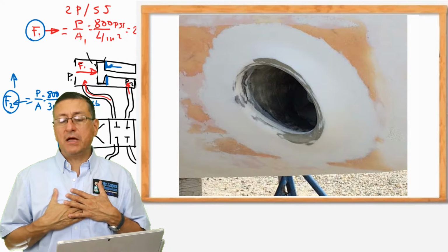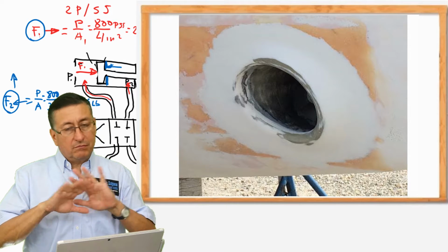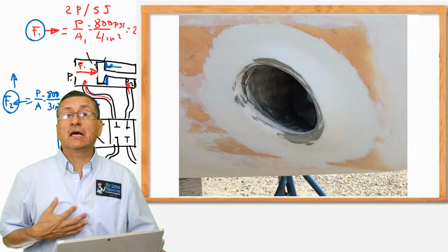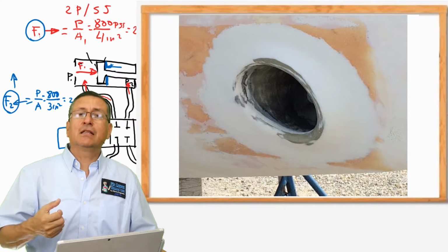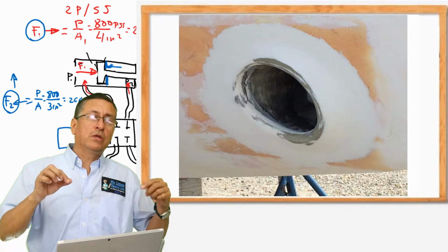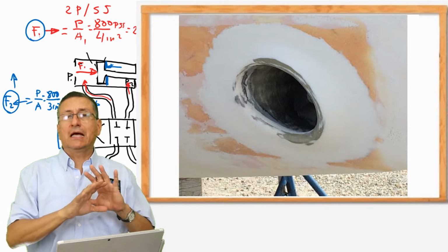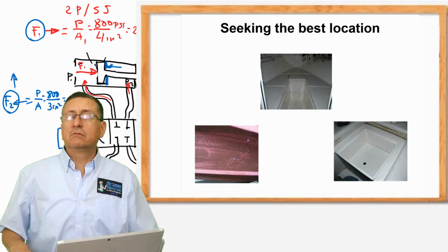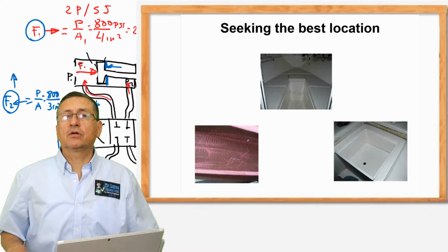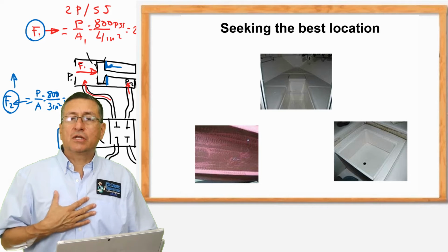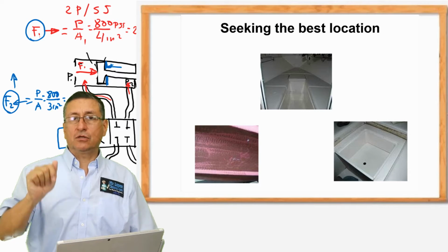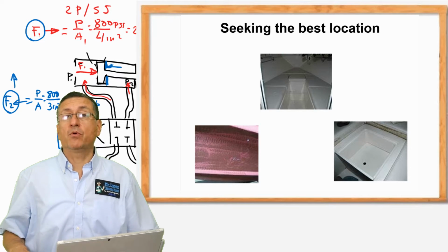Normally, I have a friend of mine who installs those tunnels for me, and after that I install the bow thruster, I do the wiring configuration, I install the electrical cable, everything, the batteries. I install the bow thruster, but I use a contractor specialized in fiberglass to do the hole and install the tunnel. That's very, very important.